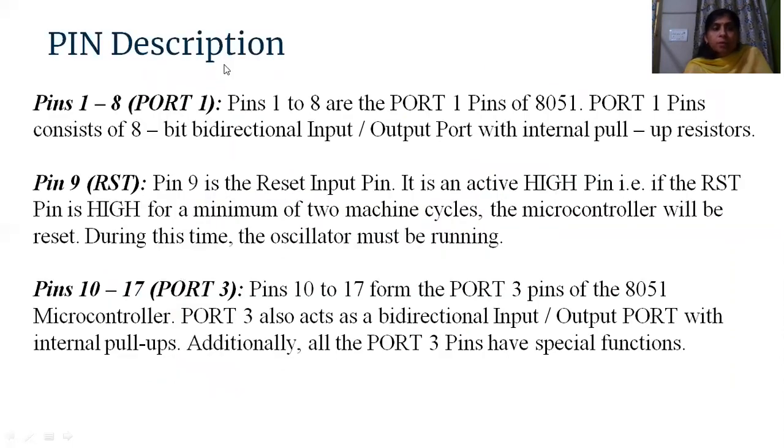This is the pin description. As I have told you, pin number 1 to pin number 8 are port 1 pins. This consists of 8-bit bidirectional input and output ports for taking input and giving output to the 8051 microcontroller.